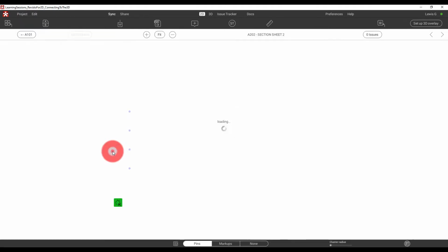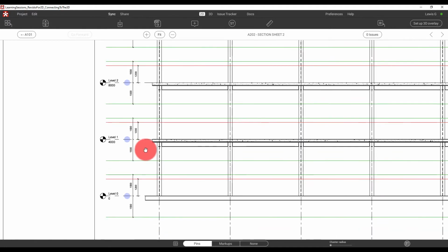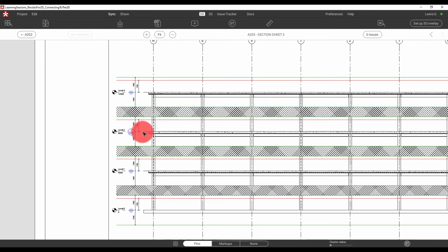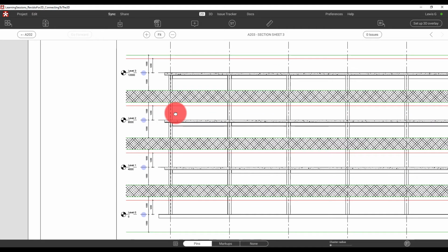That's all pretty straightforward, but then on this next sheet, what I've done is I've replicated those view ranges across all the levels. And this is where it gets really interesting because the view ranges, as discussed, quite often are just generated from a template. They're not really thought about. And if we look at this next drawing, I've then highlighted these areas. And these are basically areas that are dead spaces that the drawings do not pick up.